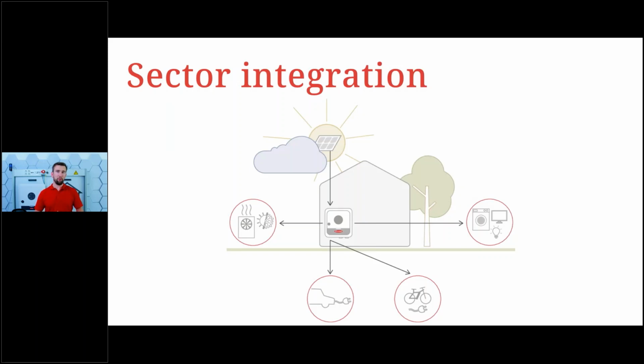When do we actually want to maximize our own consumption, the amount of electricity that we use of the electricity we produce in our PV system? Well, that is based very heavily on the question of the energy tariffs. If energy is very expensive when bought from the grid and we get very little in the way of feed-in tariffs, then obviously we want to use as much as possible ourselves and only feed in the surplus above that.